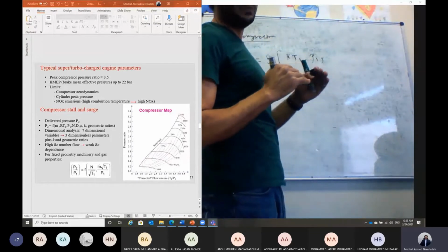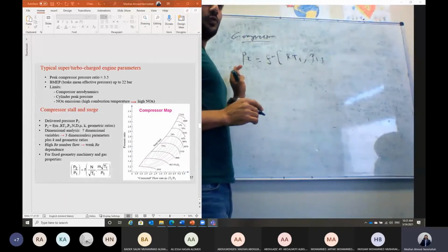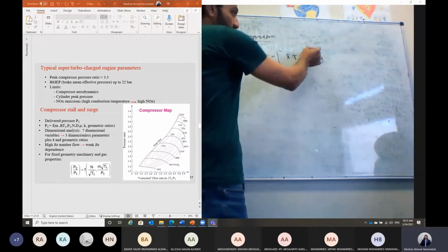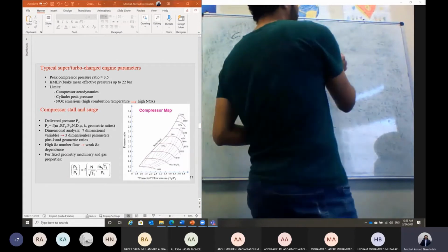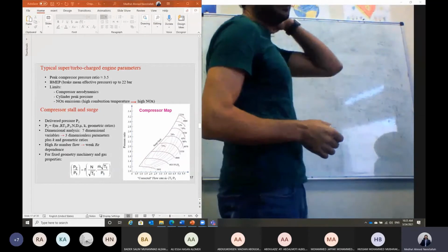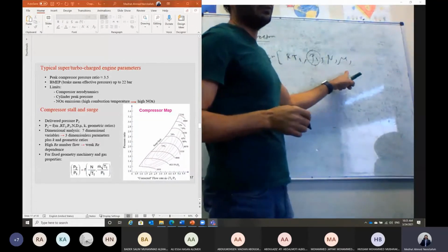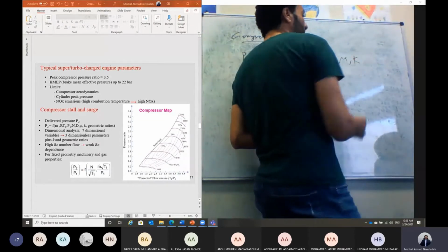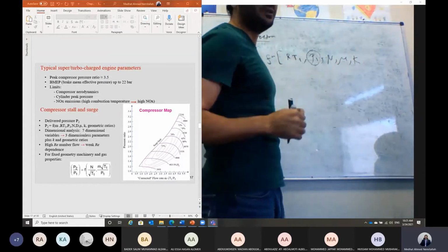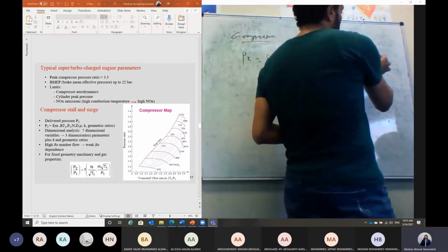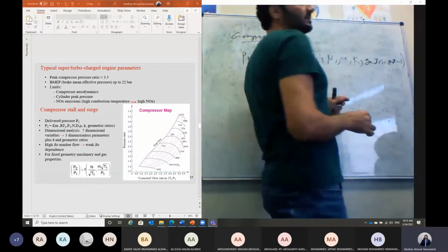If we put this turbocharger at the top of a mountain, the atmospheric pressure will be reduced. So this is also another parameter. It is a function of the RPM, the dynamic viscosity of the air, and the specific heat ratio of the air, which can change during the compression process. And we also have some geometric parameters for the design of the compressor.